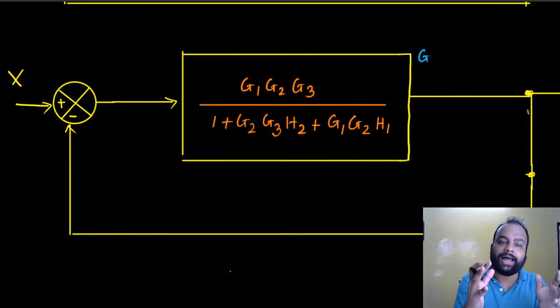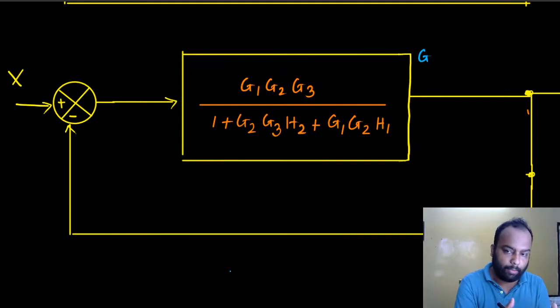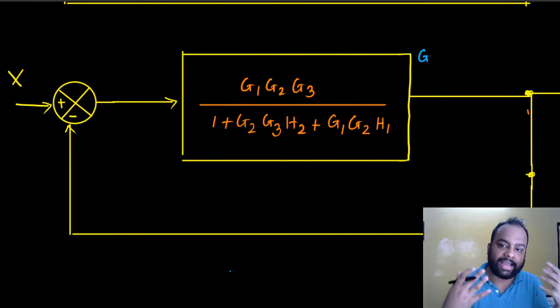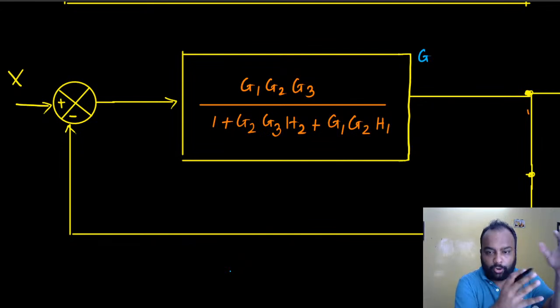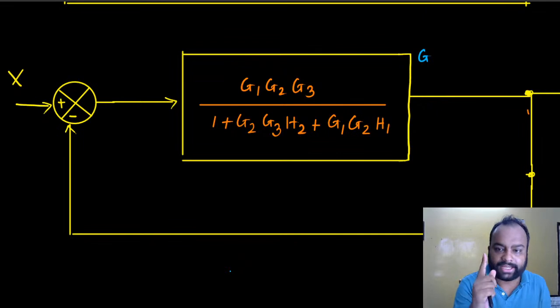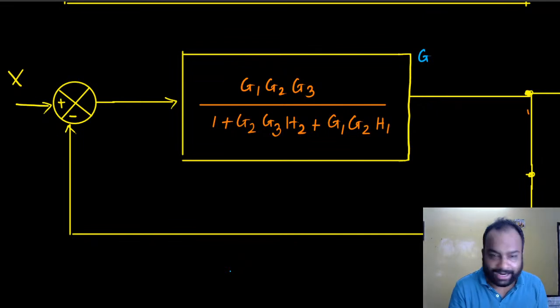So actually, while teaching, I often do this thing. I take a single system and simplify it using, say, a block diagram reduction technique, and then I solve that using a signal flow graph, and the results should agree. We should end up with the same transfer function at the end, right? But signal flow graph is of course a more modern and single-step technique. So you have to do some calculation, but after that, in a single step, you end up with the result. Okay, right? So that's one of the things.